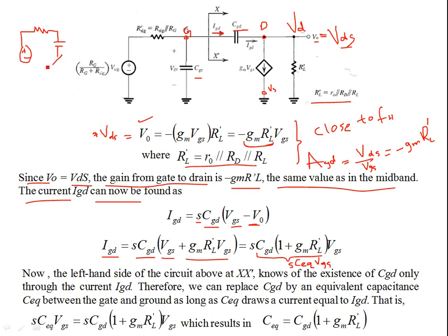And we can very easily develop the transfer function there, right? This is going to be your R signal prime, and this R signal prime has the same value which is written over here, the same Thevenin resistance, and then there will be a parallel combination of CGS in parallel with C. Basically, in parallel, you just add it up. So C equivalent is this expression.